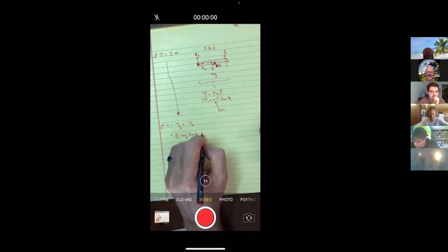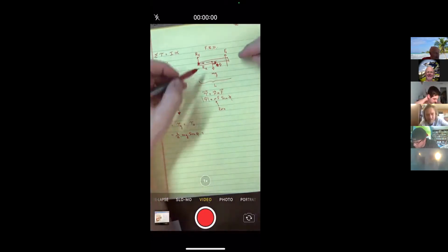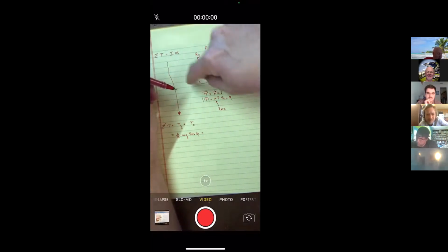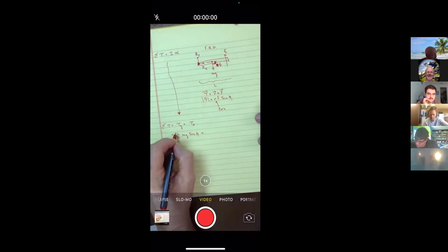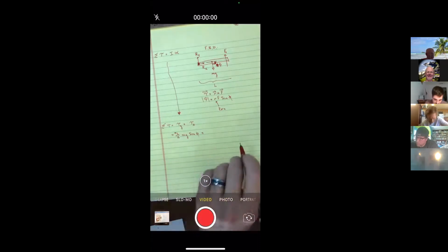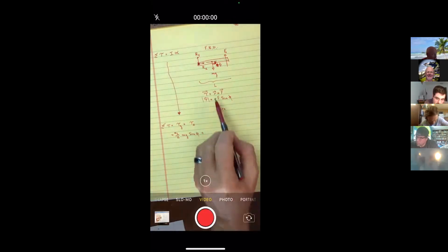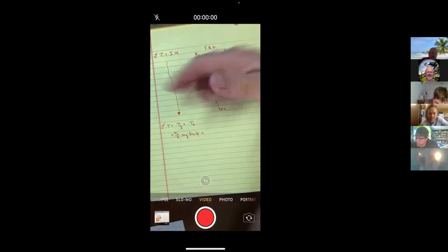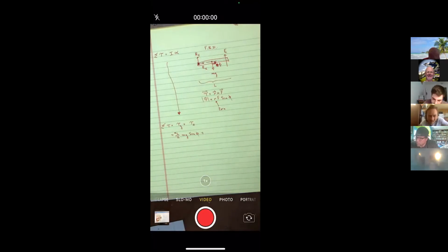Let's talk about the torque. Oh, and I guess I should keep an eye on the sign of it. Let's see, gravity would be pulling it in a clockwise direction. And normally we call clockwise a negative motion. So I'll stick to that tradition and put a negative torque there. Because remember, this formula here is the magnitude of it. We have to either look at the picture or do our little right-hand rule to get the direction of that torque.